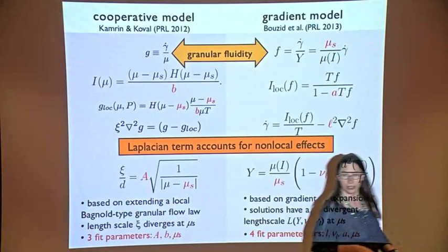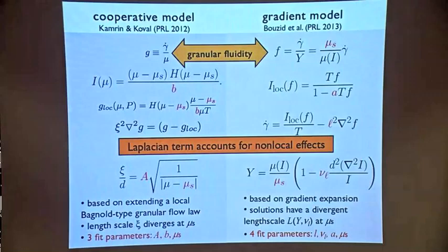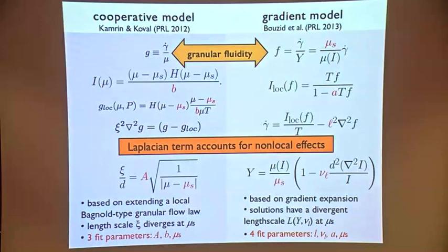Locally, if you're below the yield stress, you shouldn't have any fluidity, nothing can flow. But the idea is that, in fact, that's just a situation in one location. Any little bits of drama that happen here annoy particles across the system. So the way the non-local effects are put into the problem is to say that the real fluidity is a diffusion of the local fluidity to other parts of the system, and there's some length scale, or diffusion constant if you'd like, over which that's happening.